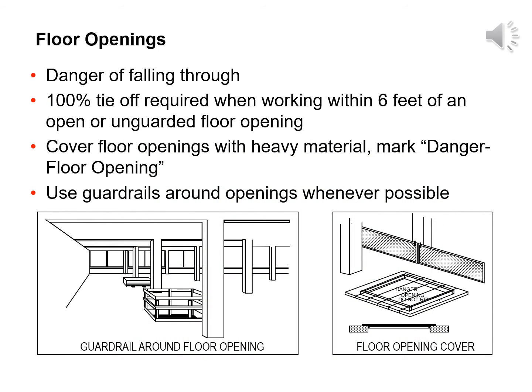Floor openings come in many different sizes and locations. The biggest danger of a floor opening is from falling through it and landing at a distance below. Another hazard is being struck by objects falling through the floor hole. Many deaths occur each year because floor hole covers are removed and not replaced, or they were constructed of materials that could not support the weight of the person or the load. You must be careful when removing floor grating on elevated platforms.